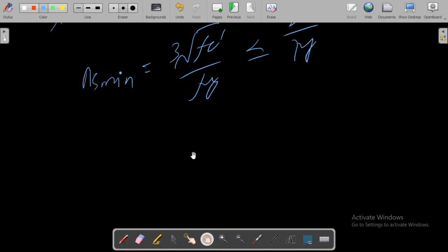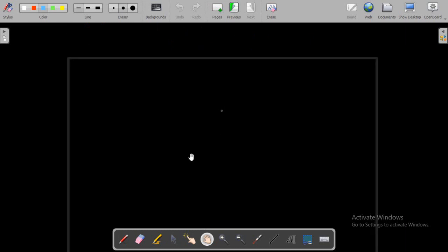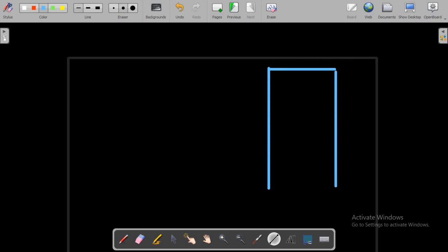After that, we can also check the cover requirements, because whenever we are using a beam section, remember there are so many checks which we can use, but in the coming example we will only check for flexure. We have torsion checks, shear checks, and many other checks, but this time we will only use the checks for flexure. We can also check this cover which we provided here.